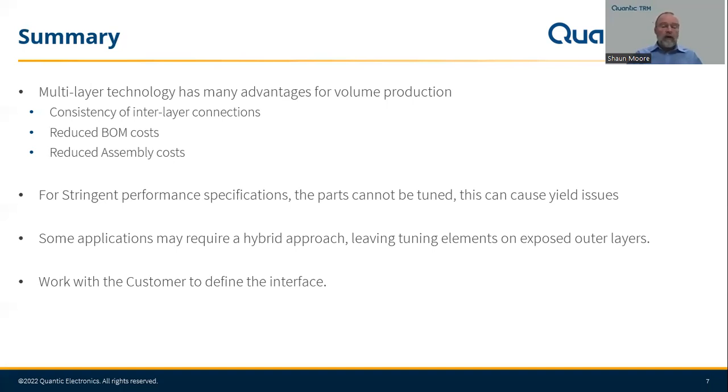There's also, especially if you're dealing with a surface mount style component, really working with a customer interface to make sure that the interface of the passive component that's meant to be put in as a surface mount component interfaces well with the carrier or the motherboard that's being mounted to. That interface is all very critical. It's just as critical as the connector to launch interface on traditional sorts of components, and should not be trivialized. It's an important thing to make sure that both parties are on the same page.